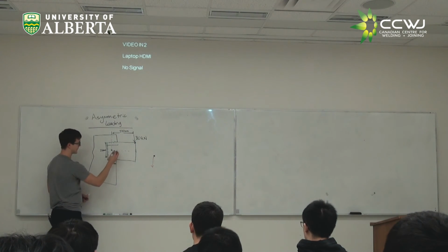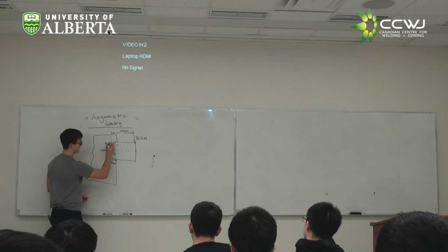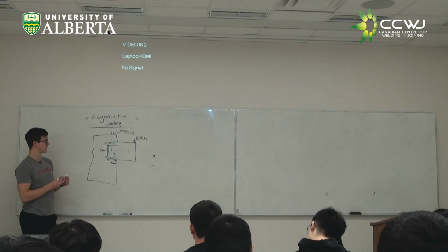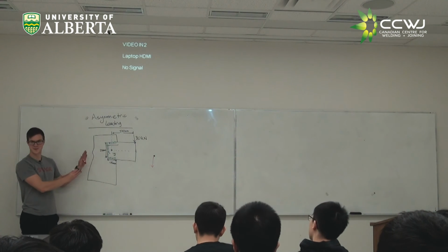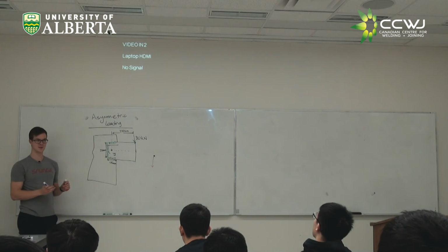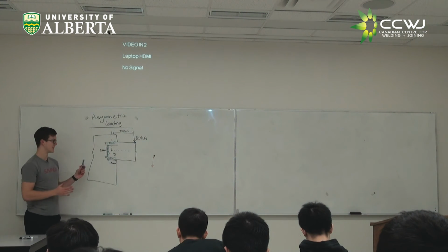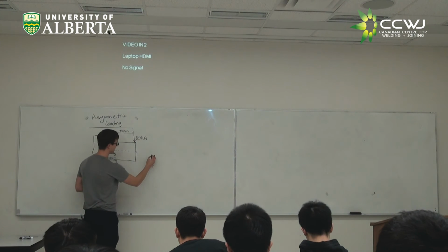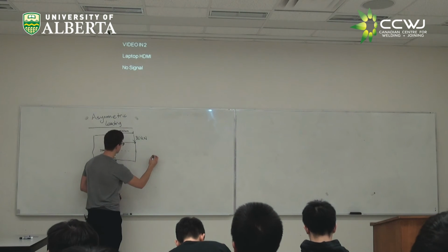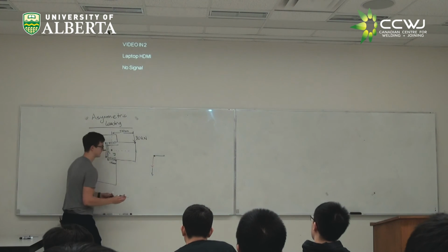And that moment, in a diagram that was already drawn before, is going to be resisted by forces acting through the welds. In concept, this is all we're going to be doing. Does everyone understand why? Are you with me up to this point? Yeah? So we end up with an equivalent. The direction's not going to be as critical here, so I'm going to just draw them all in the same direction to make sure it makes sense.